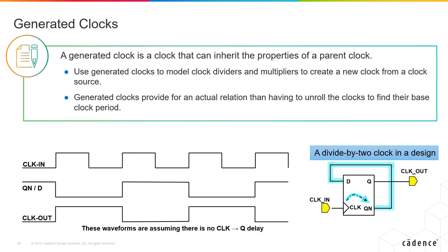Generated clocks are helpful when you want to model a particular clock and inherit all the properties, with a slew of 0.25 nanoseconds on the rising edge of the ideal clock, and a slew of 0.25 nanoseconds on the falling edge. Notice that get_generated_clocks is calling the clock when you have weird numbers or weird divisions that are happening, like 1/3, which must use floating point numbers on the clock. The calculations are harder. In the case of a generated clock, you don't need to worry about such things because you are just implying that it's 1/3 of a master clock.